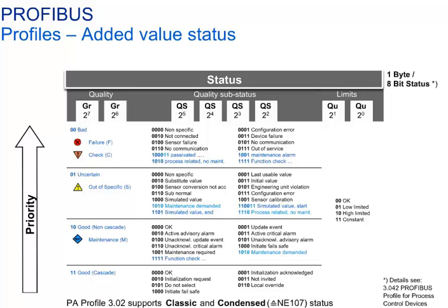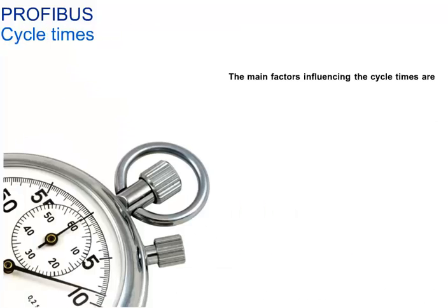The great user benefit is that, for the first time, profound information from the field devices and their connected peripherals like valves, pipes, and so on can be transmitted to the distributed control system. Targeted maintenance is thus made possible. This kind of data transmission is not available for 4 to 20 mA devices.